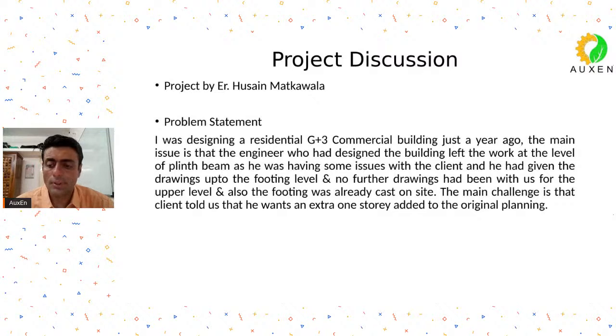Yes, anyone, if they would like to quickly comment. I hope you got it, what is happening. So let us say, when you got this project from the client, the construction work till the plinth has already been done, and now the client wants to add one more story. Okay, so the footings have been cast, the plinth level beams have been cast, the columns have been cast till the plinth level, and now you are asked to add one more story and do the rest of the design. So as a design engineer, how will you proceed?